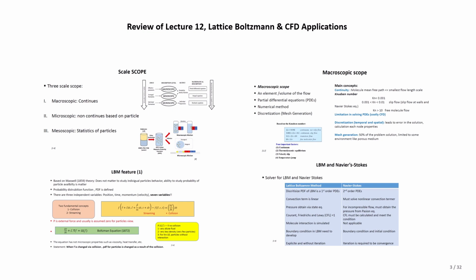We pointed to some important features of the lattice Boltzmann equation. First of all, it's working on the mesoscopic scale, and we said this scale is placed between the macroscopic and microscopic scale. We are not following the particle like the microscopic scale.